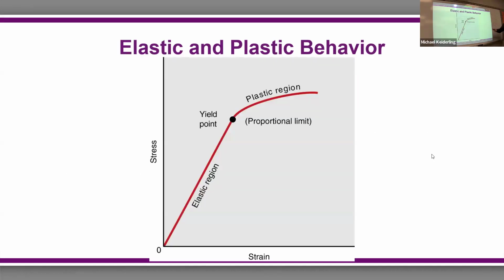So here, the yield point, where it goes from being elastic to plastic, is here. And the strength is the maximum stress, the maximum height you get. That's the mechanical strength. And you can talk about different strengths as different points on this. For this particular material, it will yield, it will deform plastically, and then it breaks.